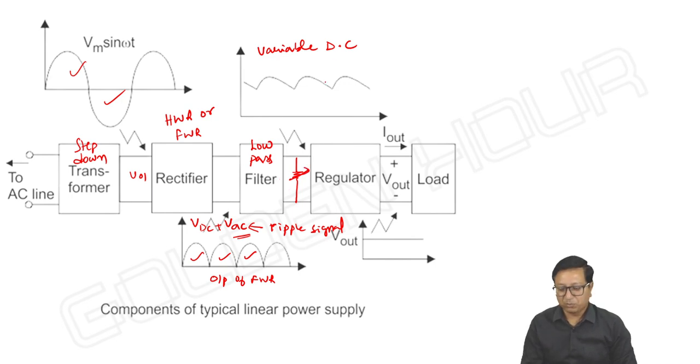Okay, and in the previous lectures we have seen, if the load resistor is connected at the output of the filter, whose output voltage is something like this, capacitor charging, discharging, etc. All those things we have seen, and whose output depends upon the load resistor. If RL is small, then ripple component is more and DC component is less. If RL is large, ripple component will be less and DC component will be more. Means the expected DC output of the filter depends upon the load resistor. Okay, that's the issue we are facing with filters.